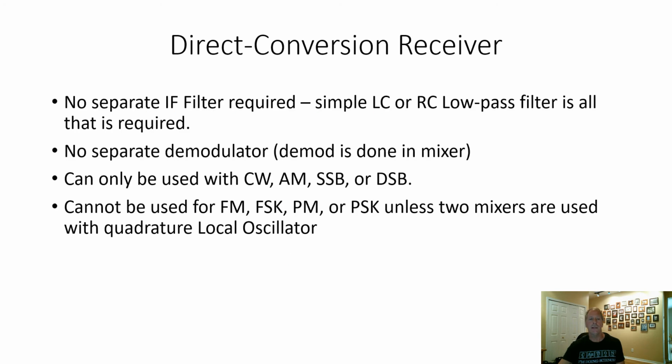The problem is you can't do FM or frequency shift keying or phase modulation or phase shift keying. You can put two mixers in, but it gets kind of expensive. But it can be used with continuous wave, AM, SSB, or DSB, dual sideband. So it's useful, pretty simple.